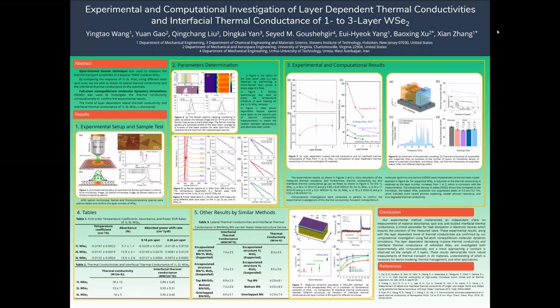Hi everyone, this poster is about the experimental and computational investigation of layer-dependent thermal conductivities and interfacial conductances of 1 to 3 layer tungsten diselenide. We used the optothermal Raman technique in the experimental part, using the Raman laser as both heat source and temperature probing tool to obtain the relation between power and temperature in the 2D materials and then obtain the